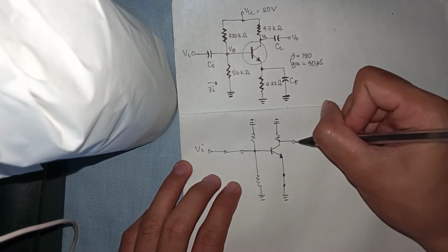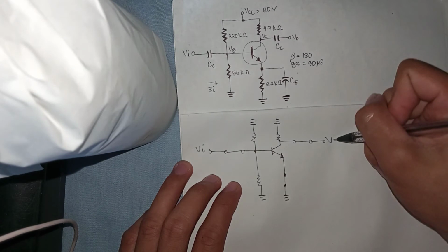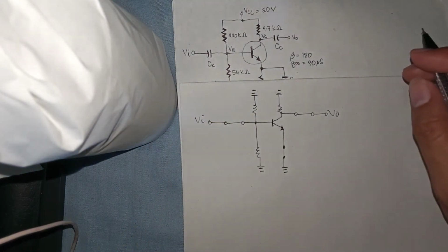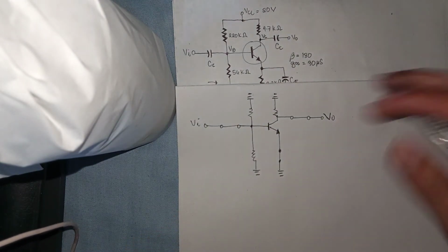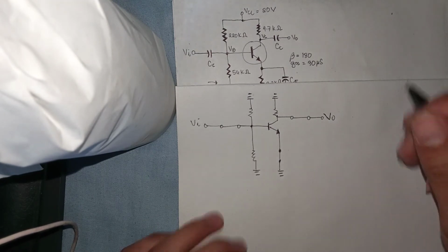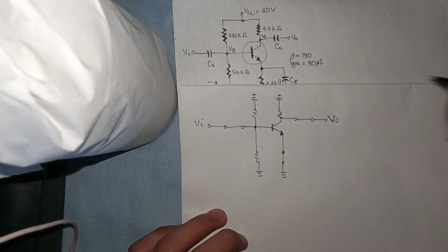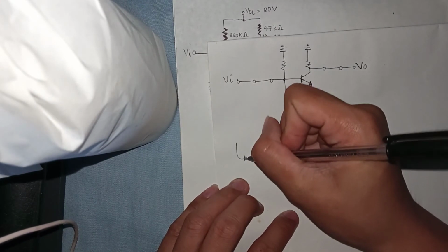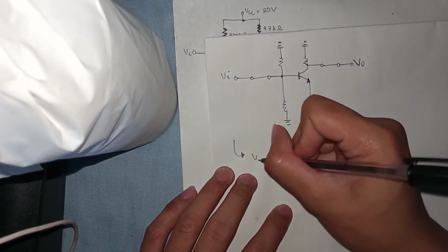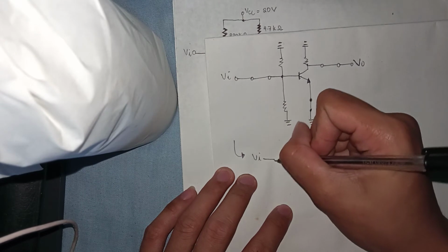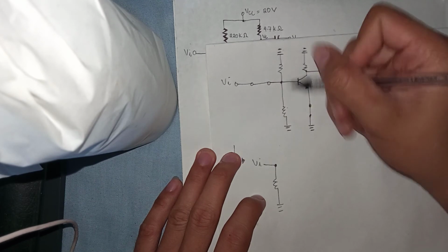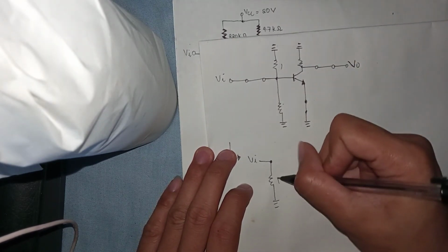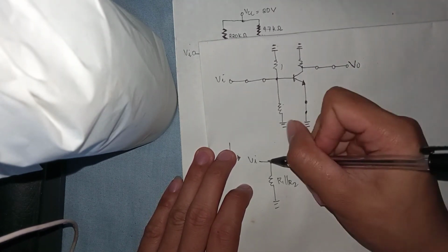Okay, for the next capacitor, from step 1, step 2, and step 3, we are here. We now draw the equivalent circuit, but we can redraw this to make it more convenient and in logical form. So from here, we can turn it into this, from R1 and R2. From this one and this one, we can create this: R1 is parallel to R2.